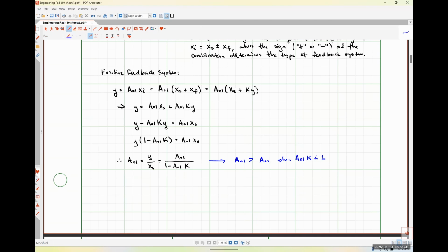Those two signals add together over and over and over again until we start hearing that high-pitched squealing noise that we call audio feedback. That is 100% a positive feedback system because the signal that's being picked up from the microphone, our voice, is being added to the signal that's being picked up by the speakers. They're combining together, and the amplitude of that system is getting larger and larger and larger, which is generating that sound. That is positive feedback in our everyday lives, okay?